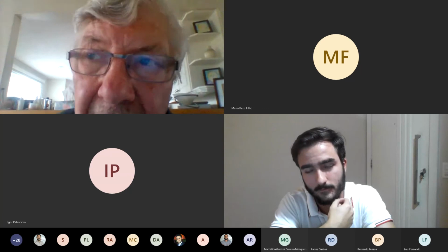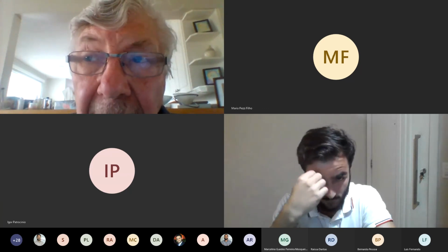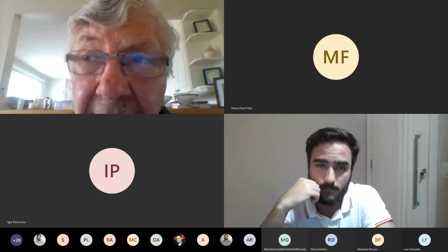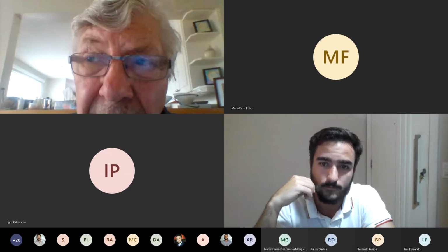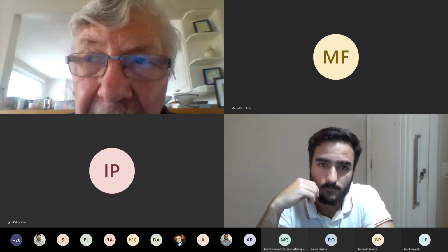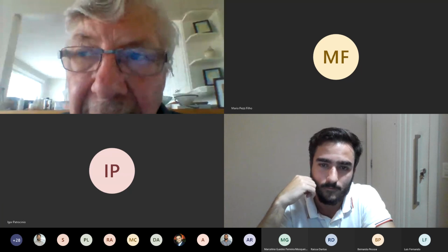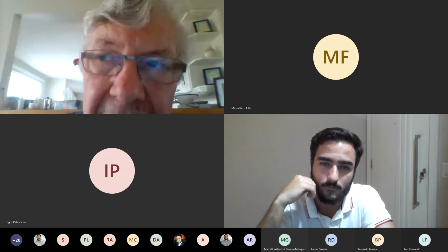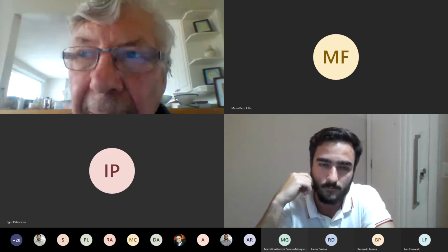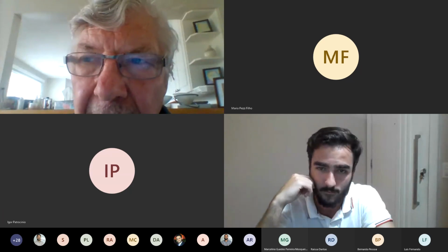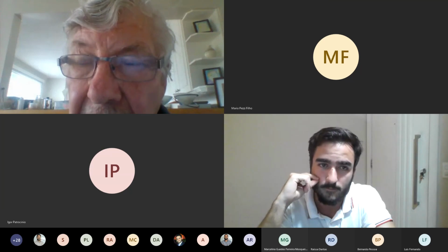So there's a big effort here in Canada to improve our ability for leak detection. Now, the physics would be that if you just use computational methods, you're limited to about 2% of the volumetric flow. If you use mass balance, it's not accurate enough. So you've got to use other systems, whether it's fiber optics or smart ball technology, acoustics. There are 5 of them that are being investigated right now. They've reported on it at the Centre for Frontier Engineering Research.